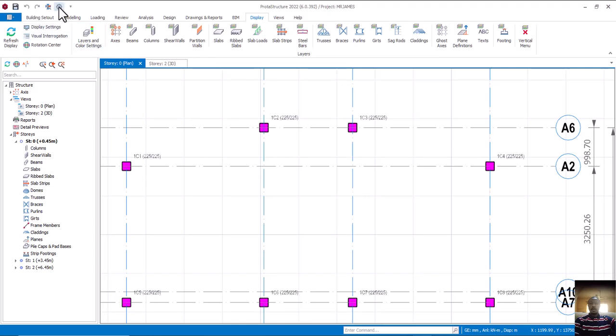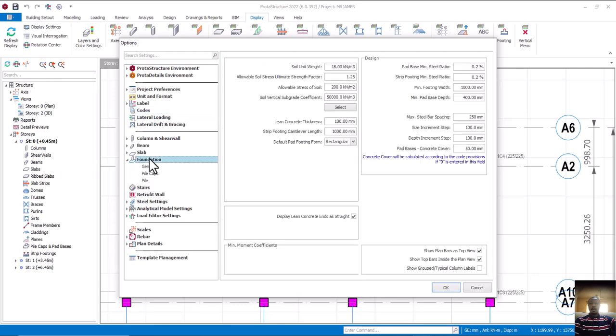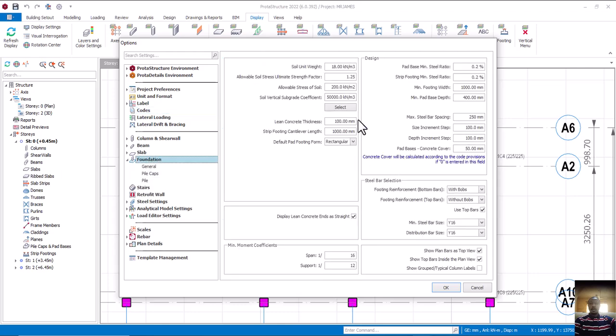For you to do settings, you come to this place now. You can see, come to settings. Once you click on it, come to foundation. Can you see we are dealing with foundation? Click on foundation, and this is where you do your settings. You can now see that this particular software, based on the one we are trying to design, actually uses soil bearing capacity of 200. But in our own case, we are using 100. Is that okay? We are using 100 bearing capacity.